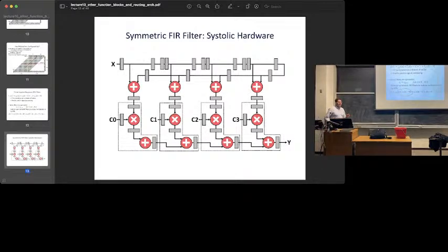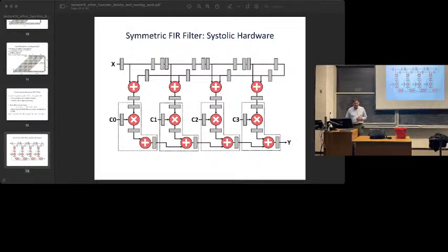So if you look at recent DSP blocks, they're not just multipliers. Here's a hard multiplier. They actually include registers on their inputs. They include adders, so they can do multiply-accumulate, registers on their output, registers in between to make them go faster. I've arranged, this basically is a Stratix 4 DSP block. That's what Stratix 4 can do. And we're using Stratix 4 again because we know the area of this block. It's been published. So all of that can actually fit inside of a DSP block, not just the multiplication. And the rest of this is to implement a symmetric FIR filter.